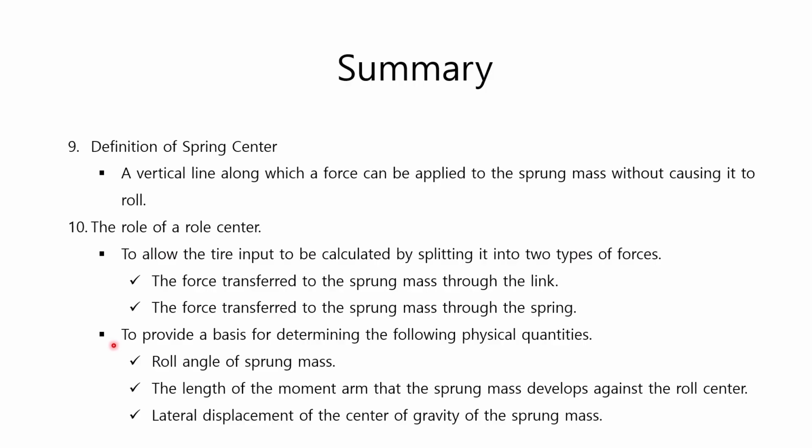Secondly, it provides a basis for determining the following physical quantities from which the load transfer can be calculated. They are the roll angle of the sprung mass, the length of the moment arm that the sprung mass develops about the roll center, and the lateral displacement of the center of gravity of the sprung mass.